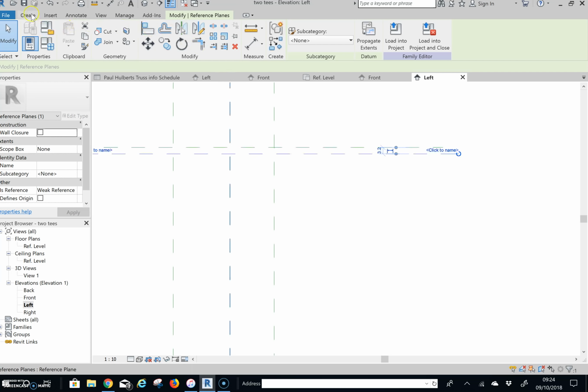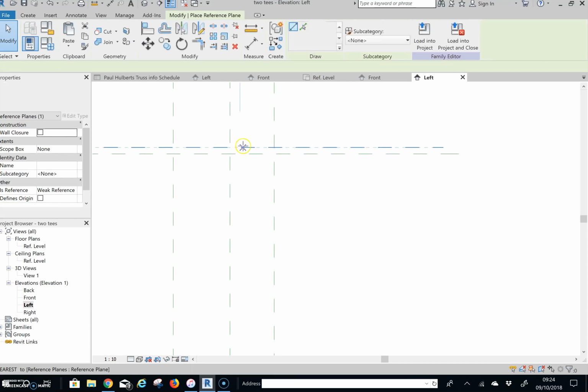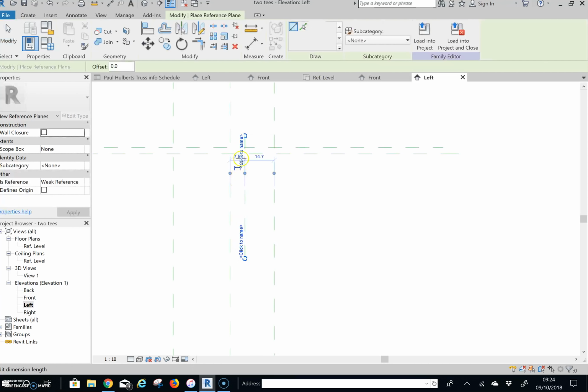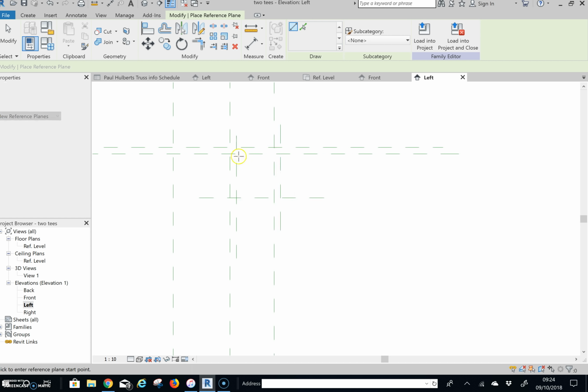I'll make another line down here, and this one would also be 3.2. This is the thickness of the, and then the whole leg is 25.4. So if I take this as the corner, I went from here, that's 25.4 from there, so it's 22.2 from here, and likewise it would be 22.2 from there. So now I can see this angle would be like this. So I'm going to draw this.